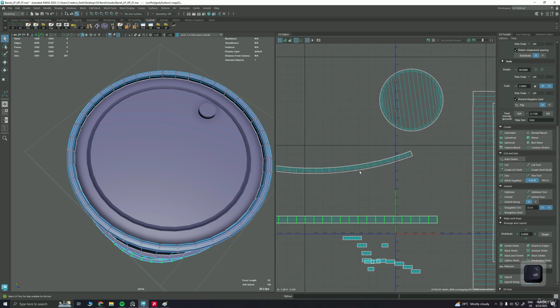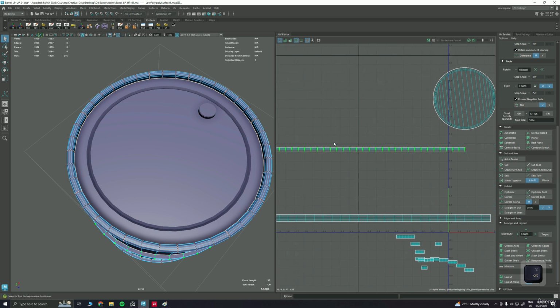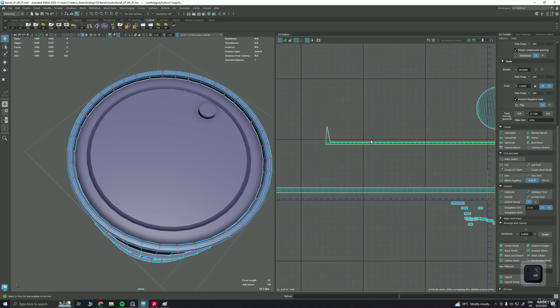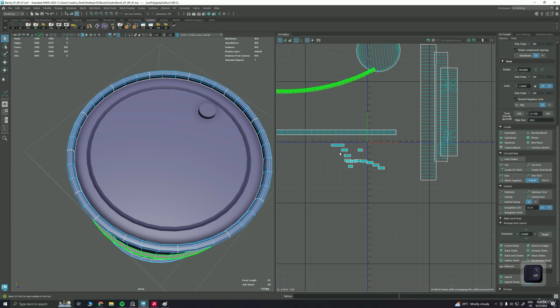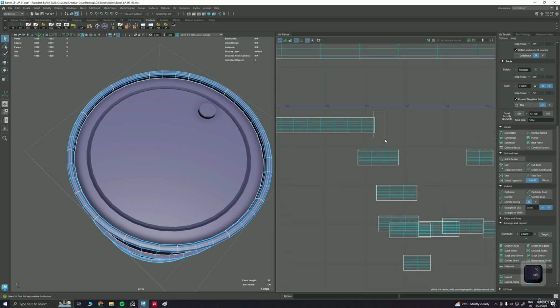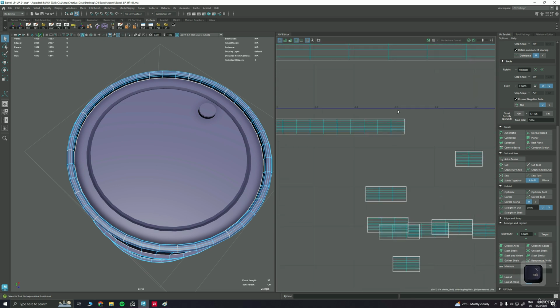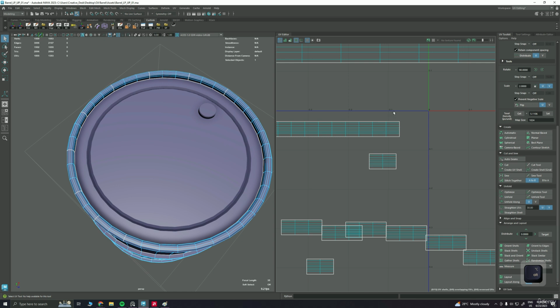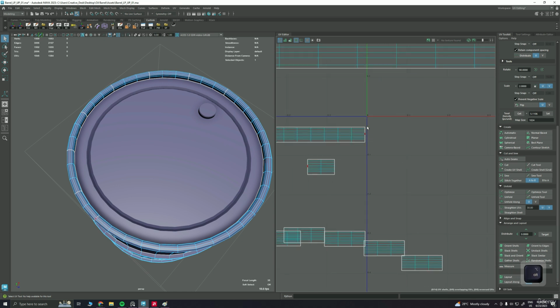So if I select the UVs over here and try to straighten it, this kind of problem arises. Okay, this is anyway not that bad, but in some scenarios it is very bad. So you can start stitching these. You can just select this, like this, and press G, press G again to repeat the command, which is stitch.